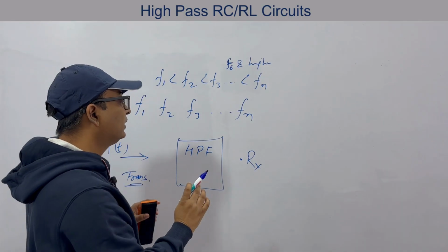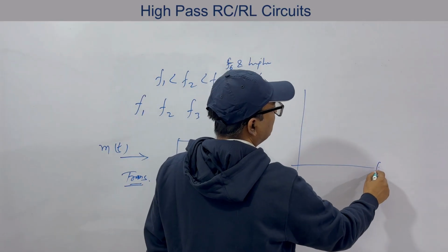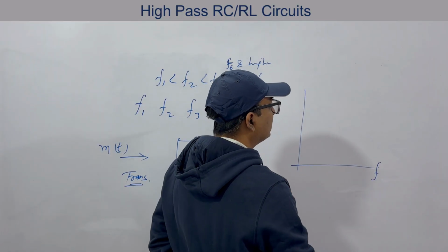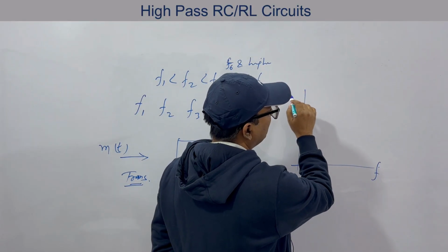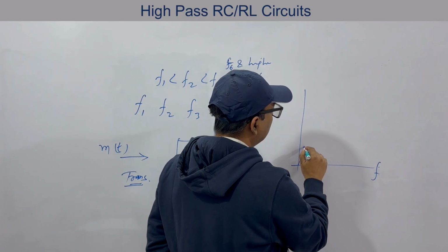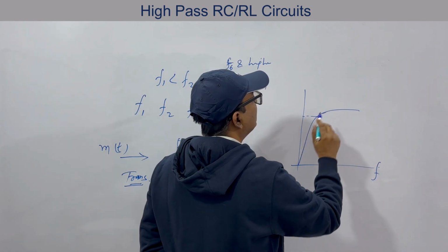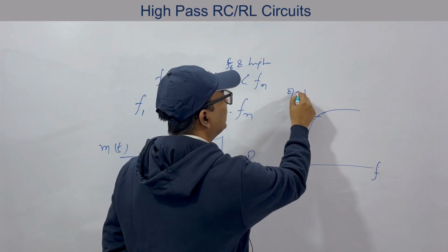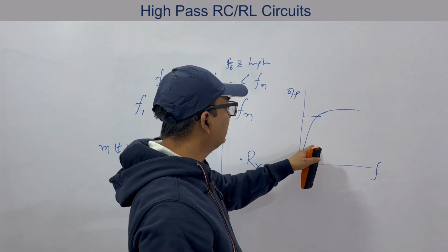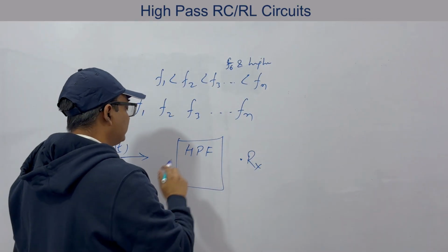High pass filter. For example, let's say this is frequency, this is increasing frequency, and this is our receiver output. That is what we receive at the output, the voltage. So with high frequency we receive more, that is like this. With frequency upper than certain limit, we have output signal, that is voltage or current. We have these signals in the output, but below that it is actually attenuated. Then this type of filter is high pass filter.